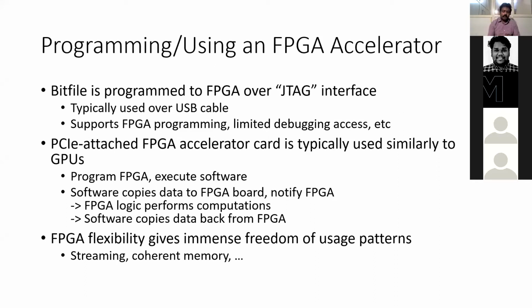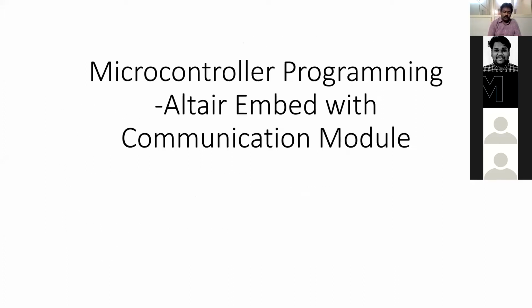So we can simply say that you choose based on the application. If you want many logical array applications with many logical functions, you go for an FPGA. For very small functions or a simple project with specific applications, we can go for a microcontroller. An FPGA needs a JTAG, which interfaces with a USB cable for programming, and PCI can be attached for acceleration, similar to a GPU. It offers flexibility and freedom of usage compared to other memory devices.